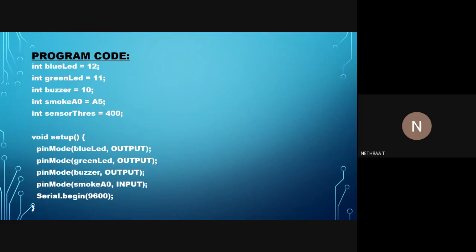Coming to the Arduino program, the green LED, blue LED, buzzer, and the analog pins are initialized to pin 11, 12, 10, and A5 of Arduino respectively. A threshold value of 400 is initialized to the sensor. The blue LED, green LED, and the buzzer are the output components, and the analog pin is the input component that is initialized in pin mode.